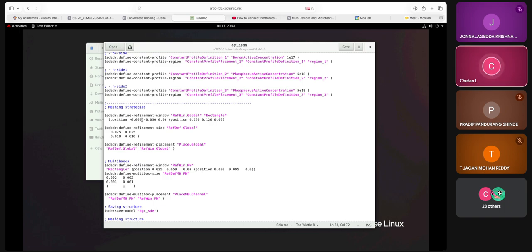but ensure that it will encompass your MOSFET. Now the other coordinate of the X direction, the maximum value is 105. So I have taken 150. And the Y direction, it is 97.5, 97 considering the electrode and all those things. So I have taken 120 to be more conservative. So my entire box is filled here. That's it, I did.